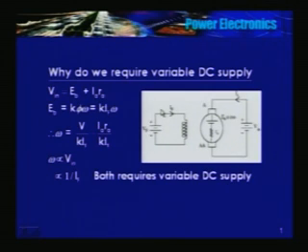Now you may say that I will connect a rheostat in series. That's what we do in our machines lab. It's basically a highly inefficient way of handling power. Please, having done a course on power electronics, don't use a resistor in series of any circuit. It's a crime. Your solution should not contain a resistor that comes in the main path of the power flow. Just not accepted.